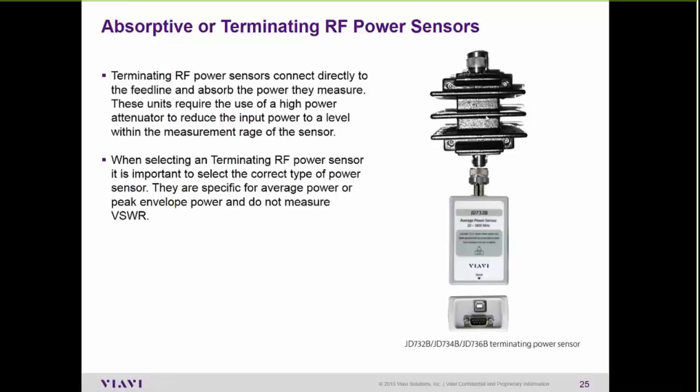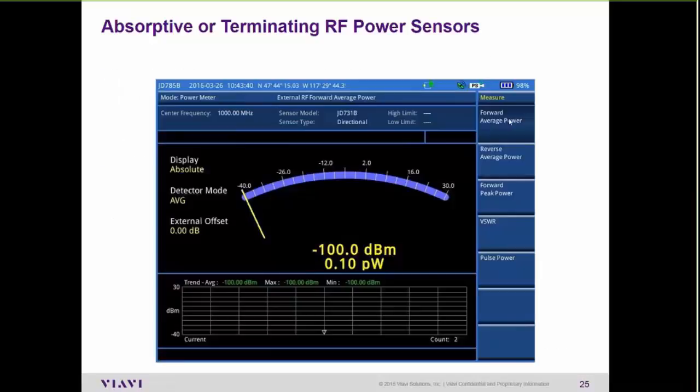So if you're putting out a 30 dB signal, it is just slightly over what the test set can rate. And there you're running right at the max limit. And so you want to drop this down probably to the minus 10 dBm range to get accurate power measurements, to account for any headroom or crest factor that's coming through the cable, so change over time. So these are the power measurements.